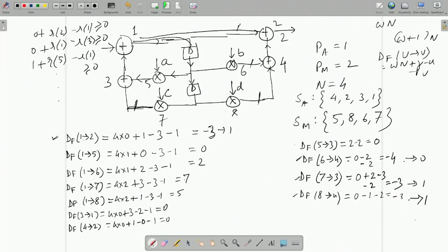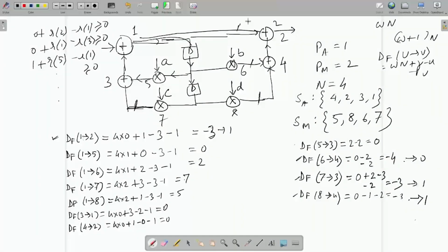But I cannot arbitrarily add delays, but if I add delays that amount to cut set retiming, I am done, because cut set retiming is a valid retiming. Now, you see the mark, I want a delay here, delay here, delay here. Clearly, if I just remove these edges, they form a cut set, because the circuit is divided into one side this way, adder 2, adder 4 at this edge and remaining part here. So, they form a valid cut set and all are in the forward direction, left to right. So, I can happily add a delay here. So, I can put a delay here.